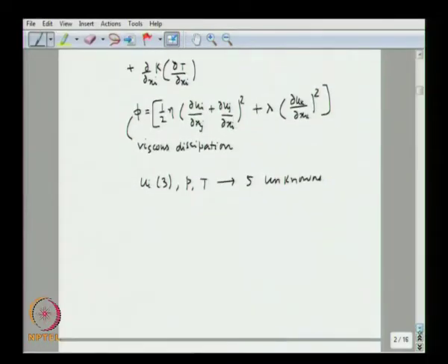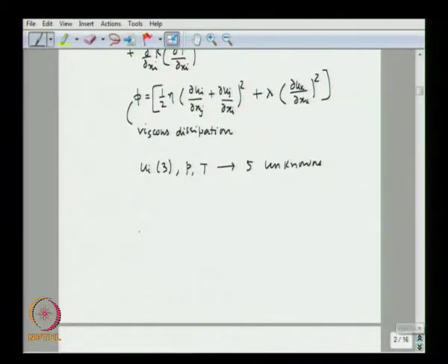The same fluid, when it flows through a microchannel and the shear rate is much above a critical value, then the Newtonian assumption breaks down. So, there is a critical value of strain rate, which can be written as gamma_c dot, equal to delta u over delta y.